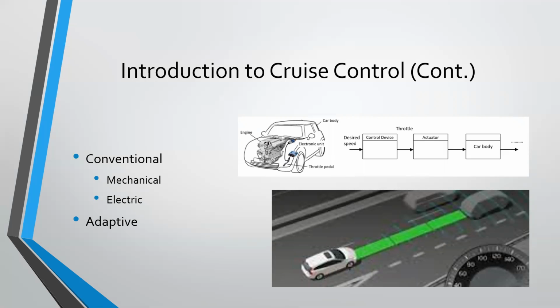Typically, this actuator was vacuum controlled and received input from the speed sensor. When a change in speed was apparent, the actuator would engage to adjust the throttle position to open or close the butterfly valve accordingly until the desired speed was achieved once again. Since the actuator physically moved the cable attached to the throttle pedal, the pedal inside the vehicle would physically move and would be problematic to some drivers if it was unsuspected.